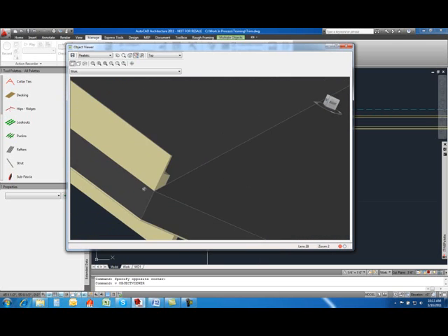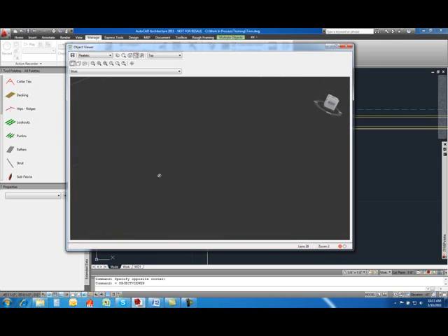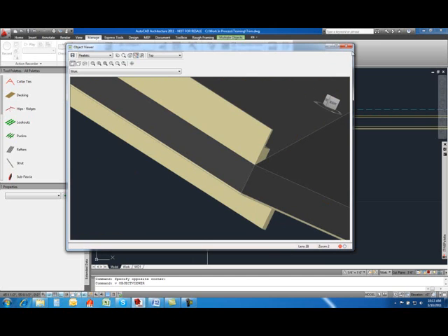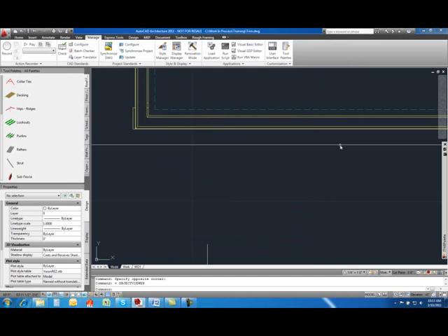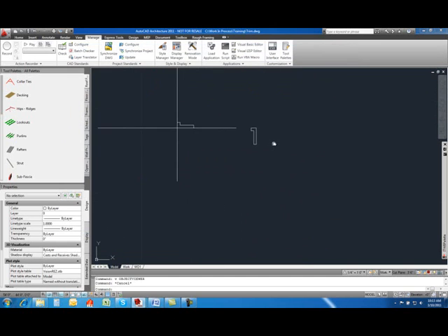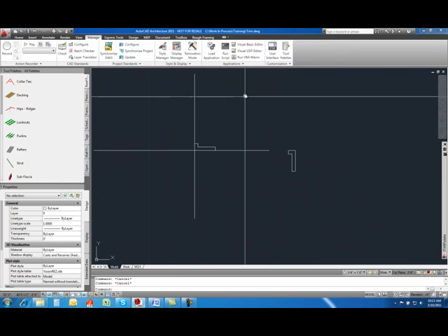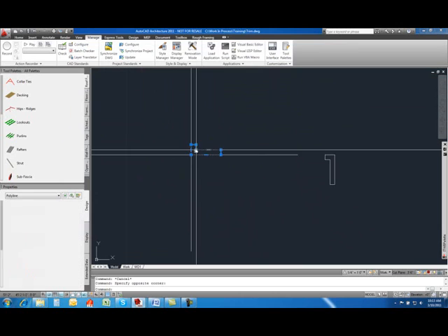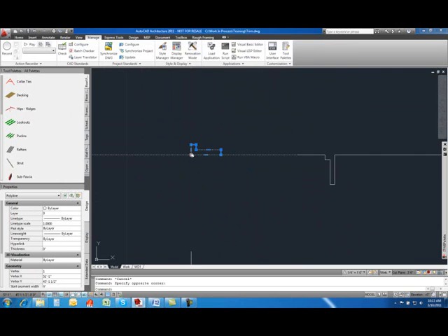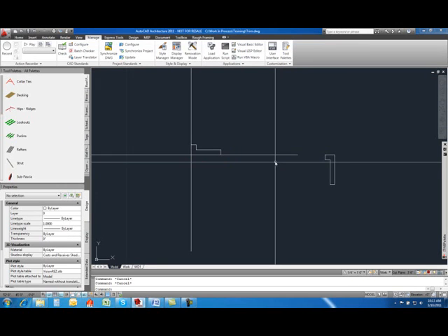It's actually upside down and rotated wrong. So make sure that if you think about it in XY coordinates, in the positive XY, your insertion point is at 0, 0, the top goes in the Y direction, the bottom goes in the X direction.